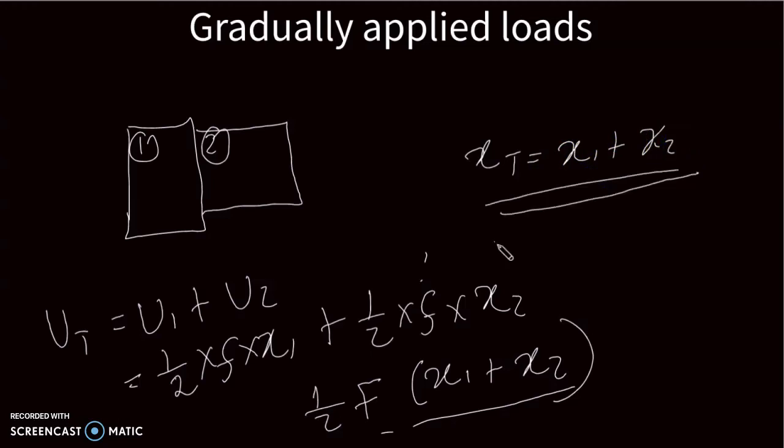So when you are dealing with an object that has more than one cross-sectional area, you need to consider each change in length separately.